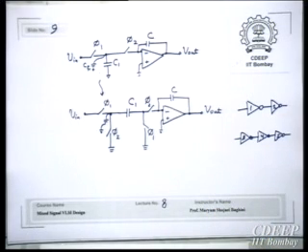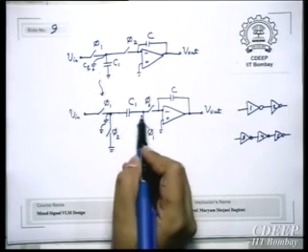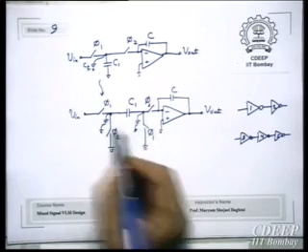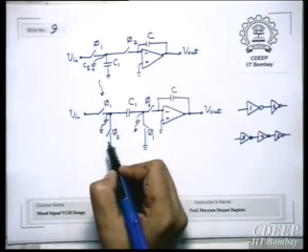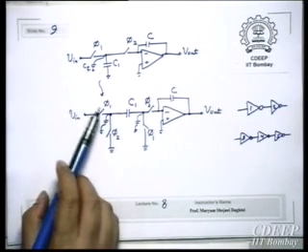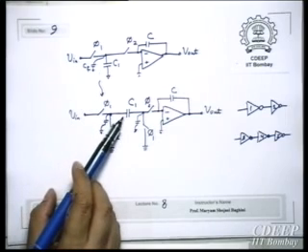So now, similarly, what happens is that always in one phase, this node which has parasitic capacitances is connected to ground. Whatever charge we have will always be grounded. It won't transfer through C. So suppose, for example, when switch phi 1 is open, that was the problem, right? Some charge will come here and some charge will come here.